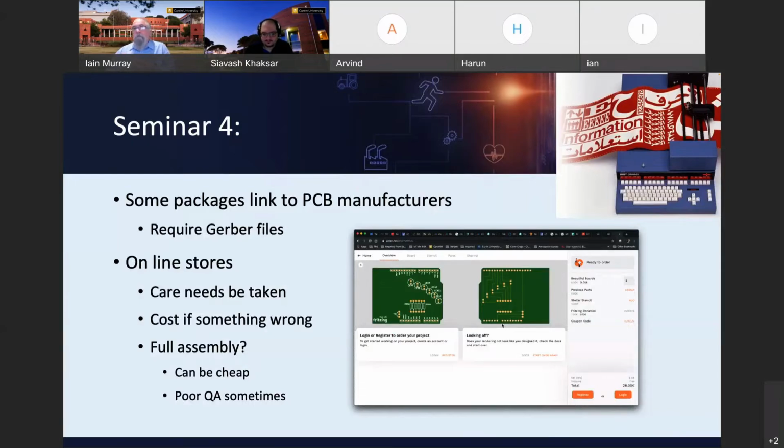If something is done wrong, you've made a design error, you've got to think about that as well. So how many do you get manufactured at one time? Usually you'd start with, like we did with that text-to-speech, a very small number to begin with. You make sure that your design worked, not so much their production, but the design worked. And if it didn't work, fix it, change the prototype, get another batch made. So that's fairly important.